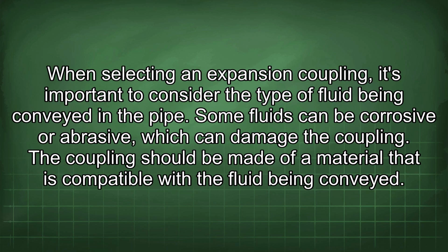When selecting an expansion coupling, it's important to consider the type of fluid being conveyed in the pipe. Some fluids can be corrosive or abrasive, which can damage the coupling. The coupling should be made of a material that is compatible with the fluid being conveyed.